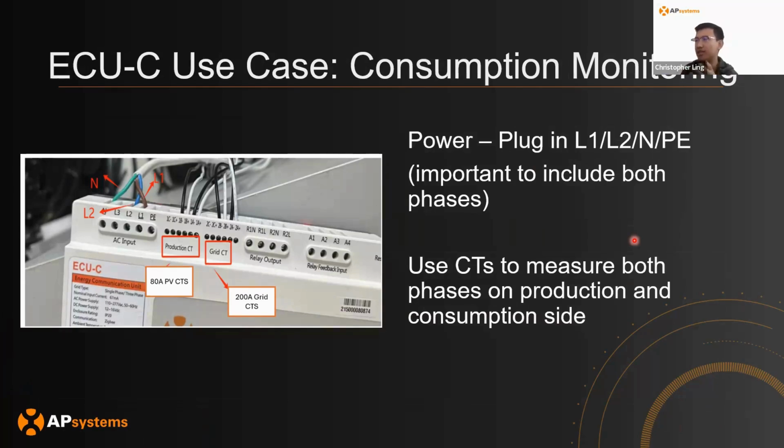And the reminder is the way that is done is through this way, where you have L1, L2 both connected, and then you have the CTs connected to all the phases. And one thing I will say, there are two caveats. One, I'm aware of other third-party systems that are able to do breaker level monitoring. This one is just a single entire house system level monitoring. And the other point also is that I believe the use case is mostly for end user knowledge.